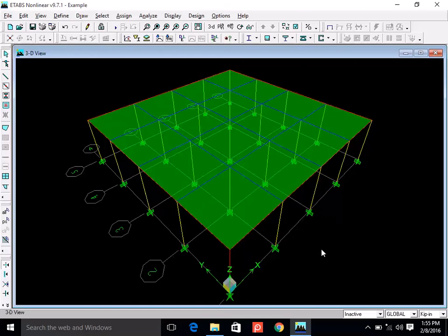If you have done analysis of a beam, then you may have chosen some nodes. You have supports, and in between you can choose several nodes, right? On every node, at the end of analysis, you will get shear force, bending moment, and displacements, right? So, when you convert a solid surface into a mesh, you are actually creating nodes, okay? And in the end, you will get the forces and displacement at every node. But this is not the only objective.